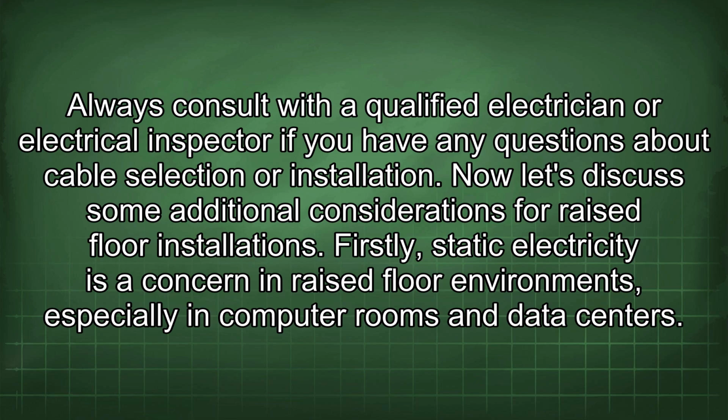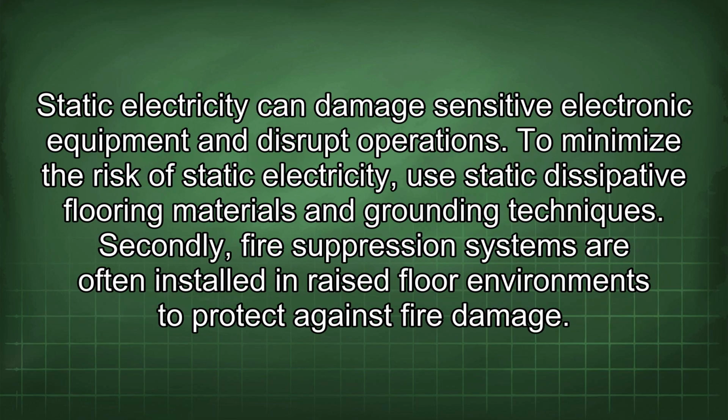Now let's discuss some additional considerations for raised floor installations. Firstly, static electricity is a concern in raised floor environments, especially in computer rooms and data centers. Static electricity can damage sensitive electronic equipment and disrupt operations. To minimize the risk of static electricity, use static dissipative flooring materials and grounding techniques.